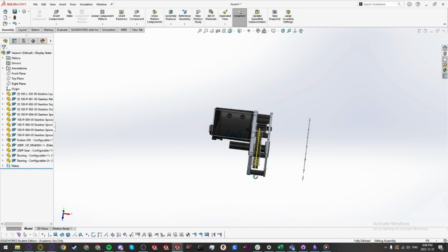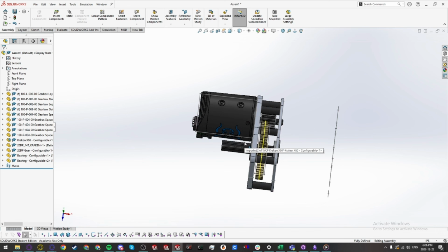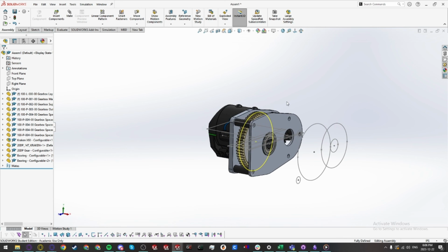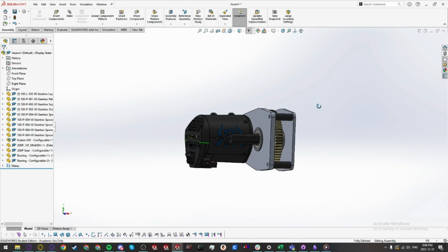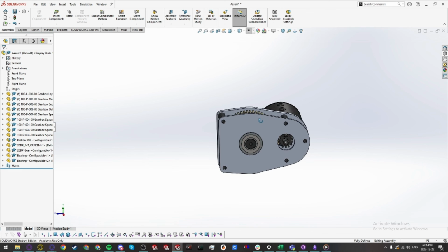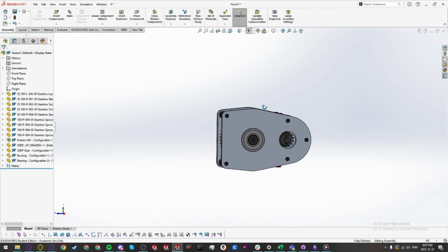Whenever I make a change to the layout sketch, everything will update accordingly. So this just makes the iterative process much, much faster. If you want to get rid of these ugly sketches, all you have to do is click the little eye icon up top, and that toggles that. So that's a quick run through on how to use layout sketches. Hope you're able to follow along.